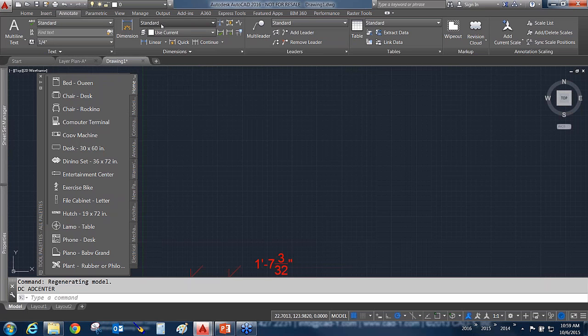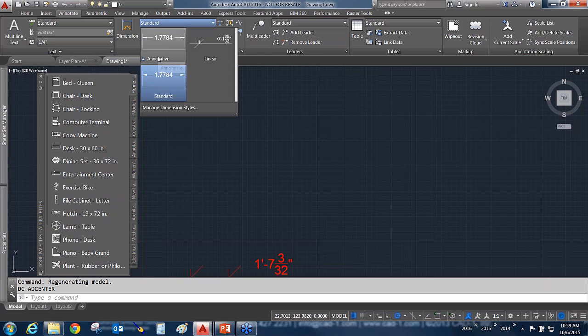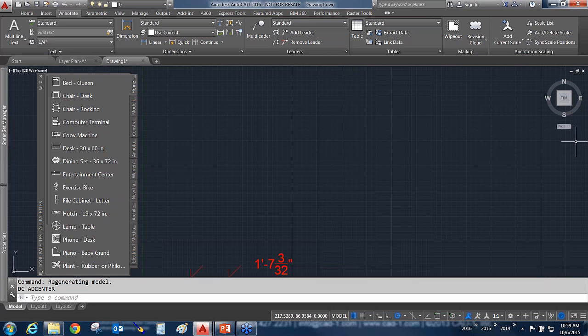Alternatively, really what I prefer to do, and we've had webinars on this before, is annotative scaling. I use annotative scaling for everything, and I work with those scale factors. That way I don't have to worry about changing scale factors for any of my styles on anything. So Brittany, that's what I recommend right there. Okay, and good, thanks for grabbing that, Warren.